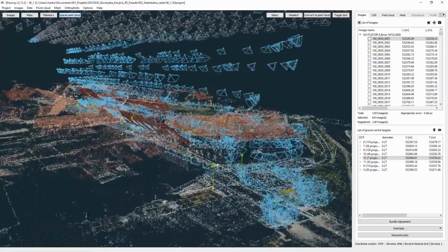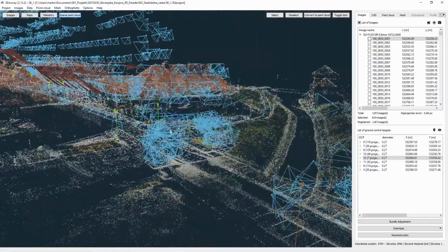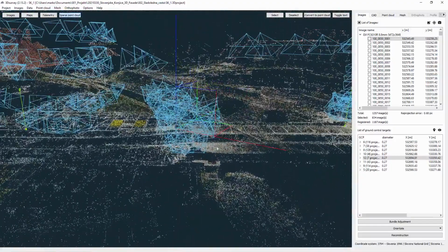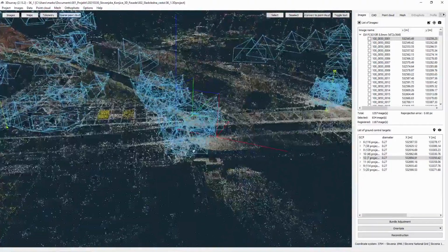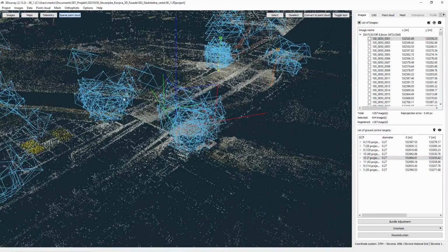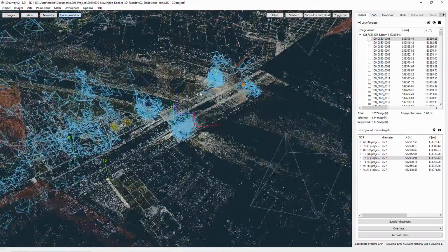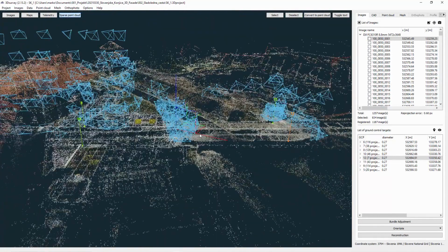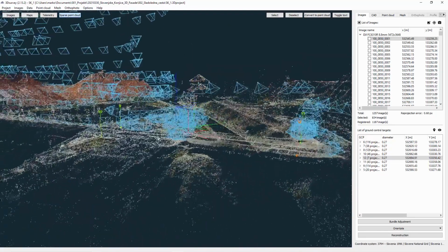We also have some special objects here. It's hard to see right now, but here are some kind of horses' heads, like small statues, 4 of them, and I actually managed to combine those aerial images from 35 meters with ground images which are triggered with the same drone, the Phantom 4 RTK. Manually I hold the drone again in my hand and trigger the camera.